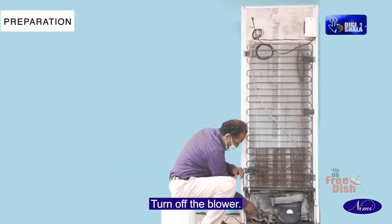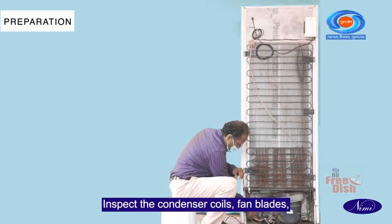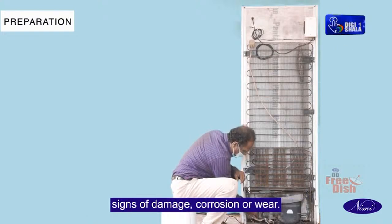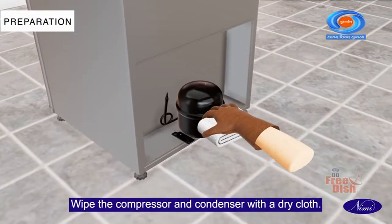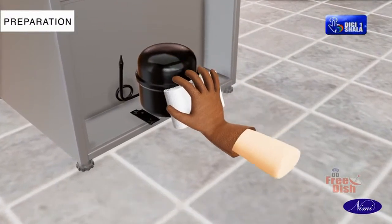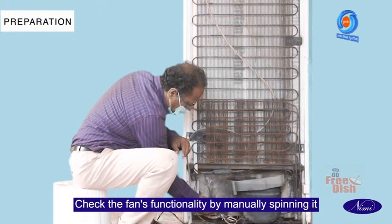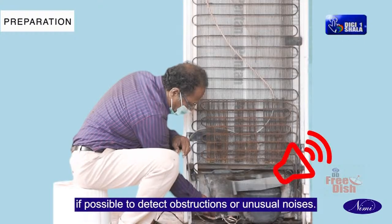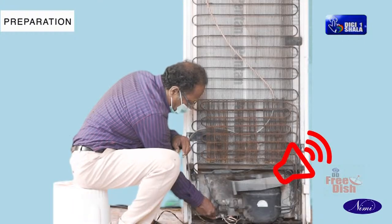Turn off the blower. Inspect the condenser coils, fan blades, compressor, and electrical connections for any signs of damage, corrosion, or wear. Wipe the compressor and condenser with a dry cloth. Check the fan's functionality by manually spinning it if possible to detect obstructions or unusual noises.